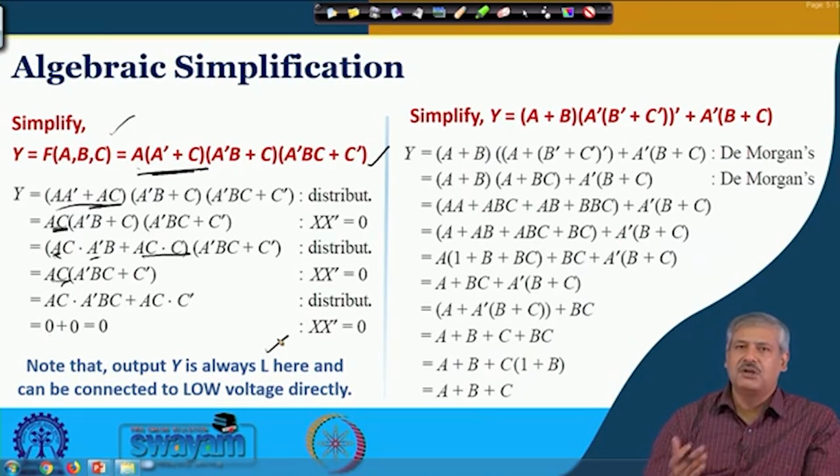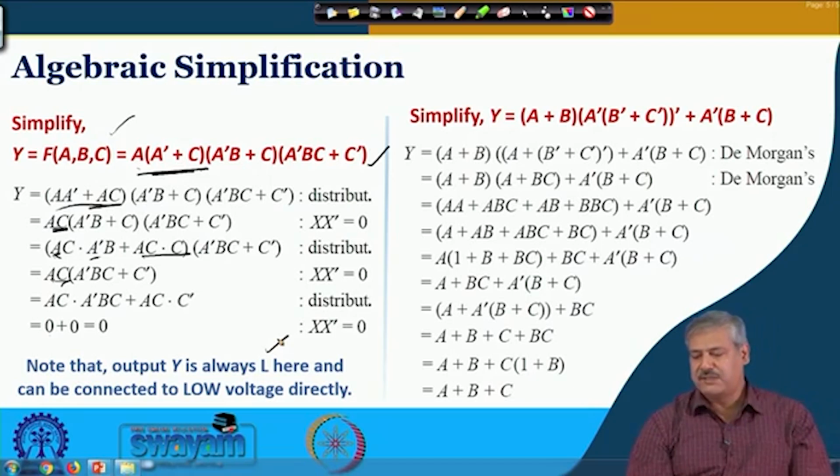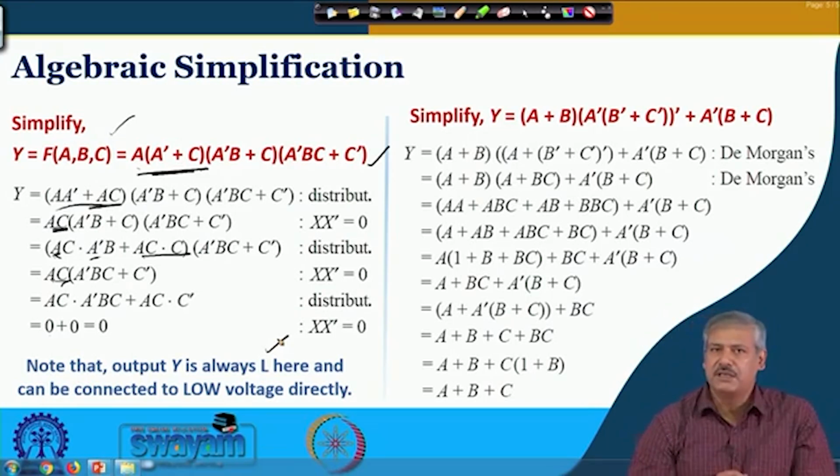And also occasionally one gives an identity to be proved, where this is the left hand side, so that this is equal to 0. I mean, this is equal to binary 0 at the end. So, there also you can find this algebraic simplification comes of use. So, another example we can see where we use De Morgan's theorem.